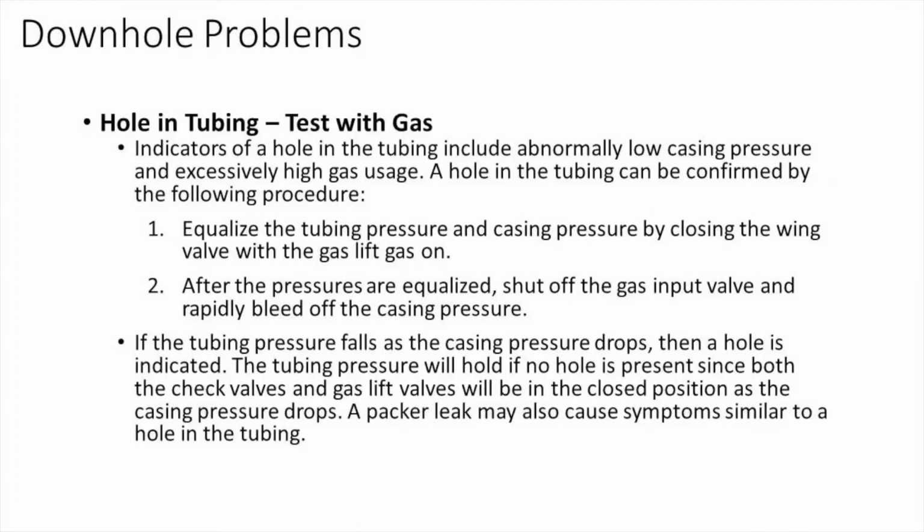Holes in the tubing. Holes in the tubing can occur with new production tubing and with older production tubing, and can really affect the overall system through loss of production and increased injection gas. Typically the biggest thing is to look for those holes in the tubing once the excessive gas usage has been identified, once the lower casing injection pressure has been identified.